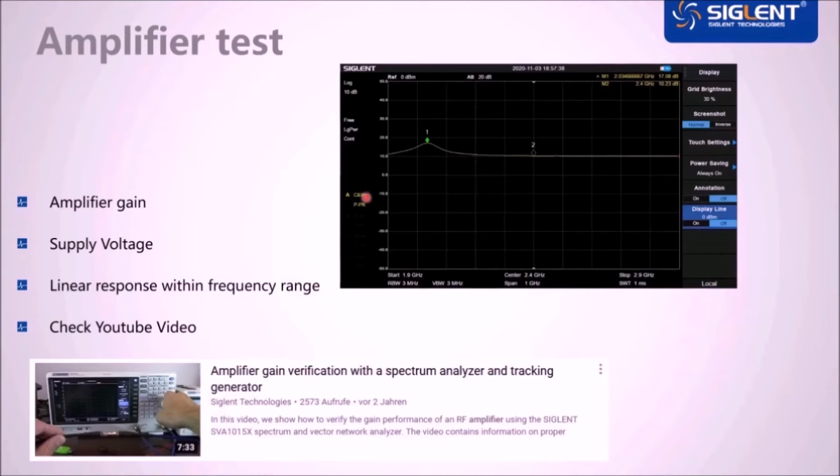For example, have a look at my measurement here. This amplifier is made to amplify at 2.4 GHz with 10 dB, which it does. But there's also an interesting peak at around 2 GHz. Actually, if you know that, you can filter it accordingly and it's no problem. But you have to find it first.